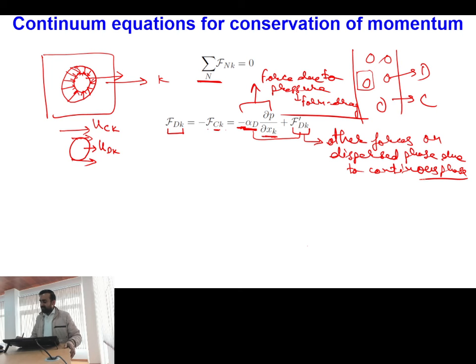One of the simplest of these is viscous drag, skin friction drag. But skin friction drag or viscous drag will come into the picture if I assume that the particle is moving in a fluid at constant velocity. If I consider the acceleration of the particle in the flow, then during the acceleration there will be other forces. One is the inertia of the particle; inertia force will come into the picture. Second, one additional type of force comes into the picture, which is called the added mass force.